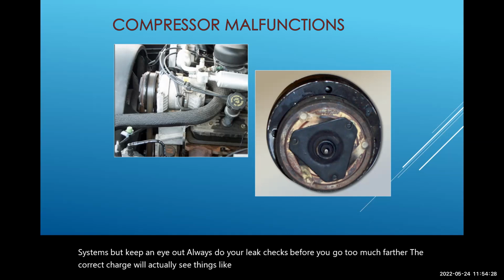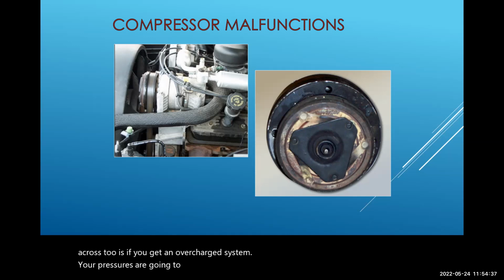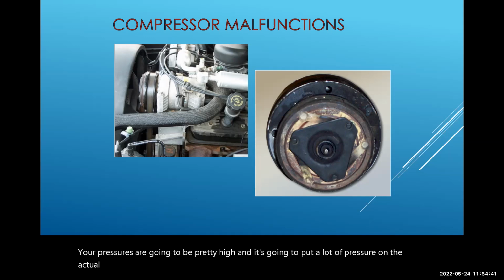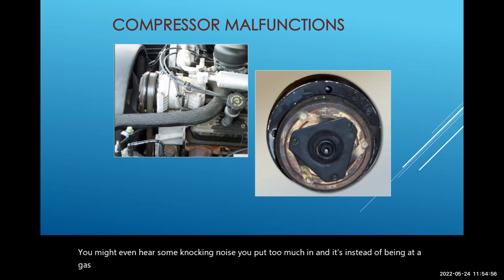The other thing I wanted to bring across is if you get an overcharged system, your pressure is going to be pretty high, and it's going to put a lot of pressure on the actual compressor, and it's going to try to do its best to move stuff around. You might even hear some knocking noise. You put too much in, and instead of being at a gas state, it's going to be at a liquid state.